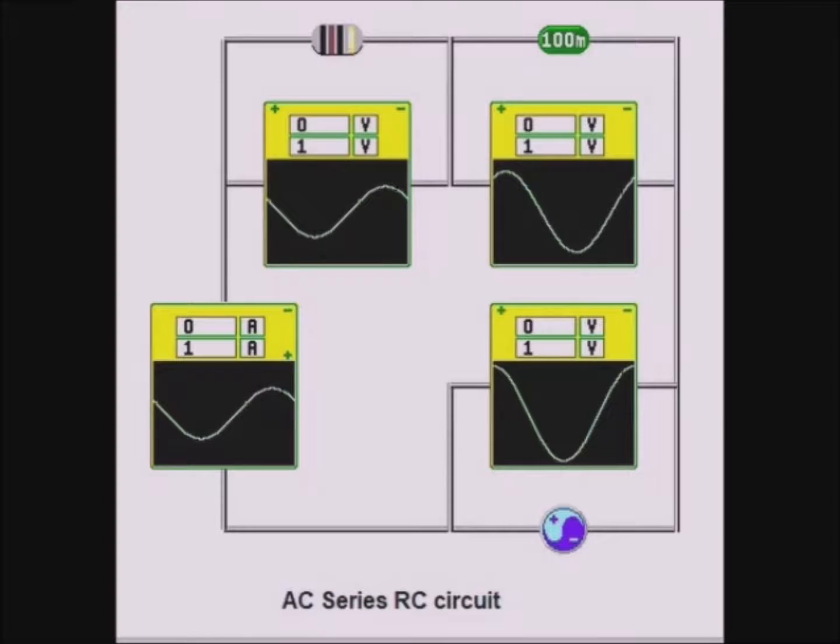We call this reactance. The total impedance, or opposition to current flow, is made up of resistor resistance and capacitor reactance. If the capacitor is large, the current is hardly impeded, whereas if the capacitor is small, the reactance is high. So the reactance is inversely proportional to the capacitance. You can try out various sizes and see the effect.